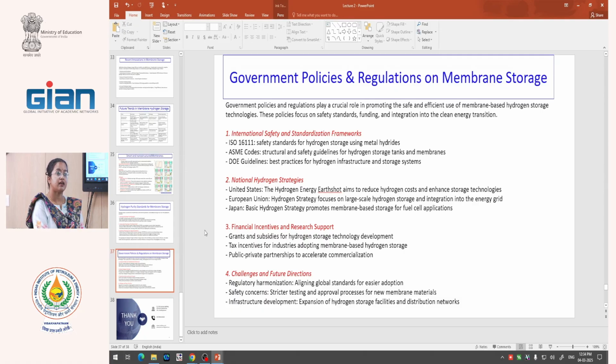Permeability will remain the same, but effectively the life cycle may get reduced and effective flux can be different. Metallic membranes are comparatively more regular in structure, so it is easier to maintain the permeability of metallic membranes. But at the same time your driving force is changing because you are changing the composition of the gas, so obviously the flux can change.